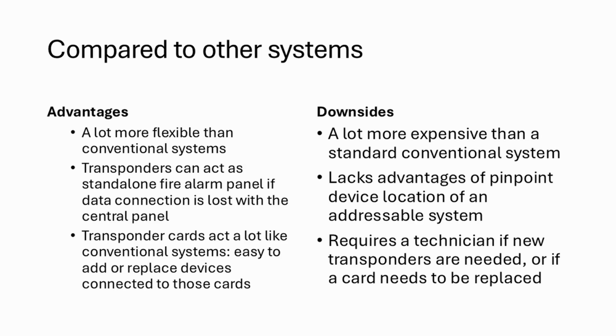On the downside, they are a lot more expensive than a standard conventional system, and they still lack the advantages of pinpoint device location of an addressable system, and they require a technician if new transponders are needed or if a card needs to be replaced.